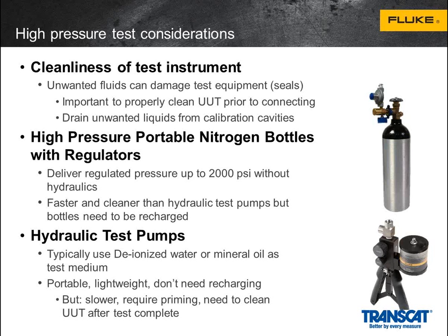So we've seen all types, but the one thing that's really important is that you need to keep that bottle charged. The other thing that's going to happen is that nitrogen has a different Reynolds number than methane, and so you're going to have to make an adjustment for that during your calibration. Again, you're trying to eliminate every possible source of error.